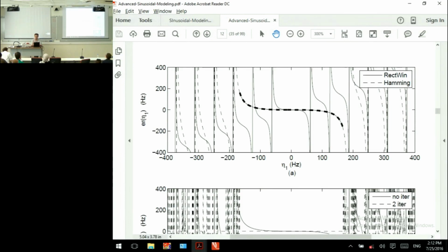This is not anymore fundamental frequency and harmonics. We will come to that. It's just one component, we don't have harmonics, just one frequency, and there is a mismatch on that frequency. For instance, say you have minus 100. Obviously, if you have a 50 hertz signal, you don't have this 100 to make a mistake. But if you are at 2000 hertz, and you are 200 left and 200 right, you make a mistake, then this has a mechanism to correct, to find the real frequency. It's a spectral estimation method, parametric spectral estimation.